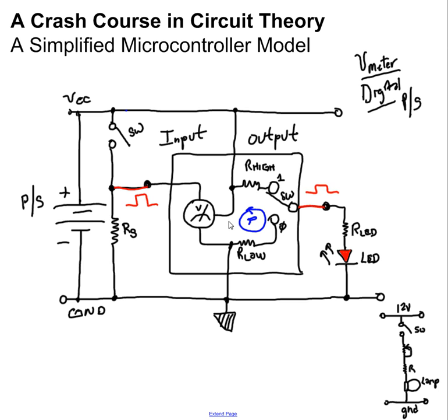Another limitation that we have to consider when we're using a microcontroller in our project is current. There are limitations as to how much current this microcontroller can provide to an output load, which means that if you need more than the specified current, then you will have to use some other technique to provide current for higher loads, such as motors, speakers, and other high current devices.